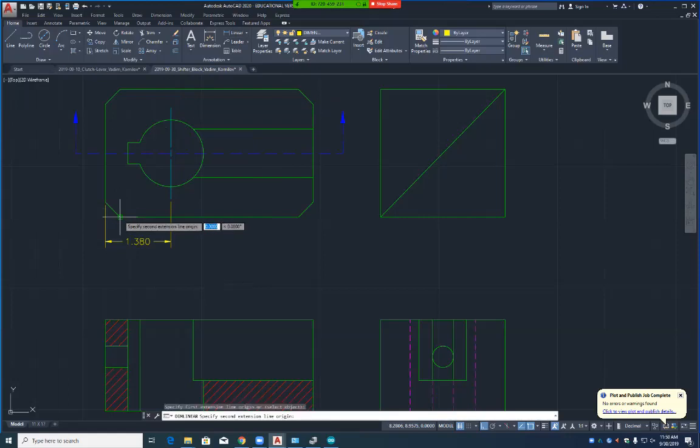So I can't get that first dimension that we tried twice to click to 0.5 out. That's how it should be right there. Then offset this line a 1/2 inch and go to that line. Another way of doing it. Sometimes you just have to do it that way when AutoCAD doesn't want to cooperate.